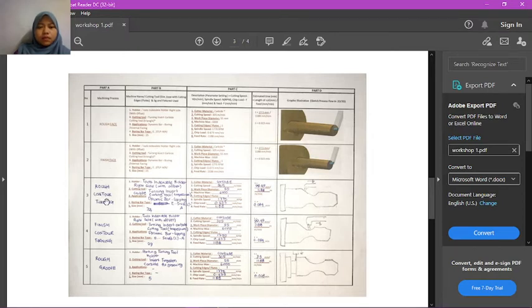And the third step is the rough contour turning. So this is the holder, cutting tools, application, boring bar types, and the size. For part C, I have listed out the cutter material, the cutting speed, workpiece diameter, and so on. And this is also the time. And I have illustrated the graphic illustration.